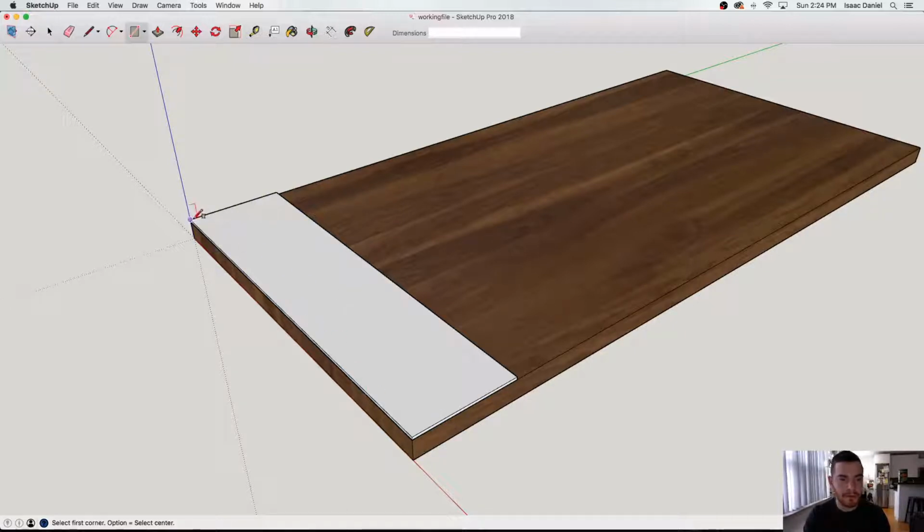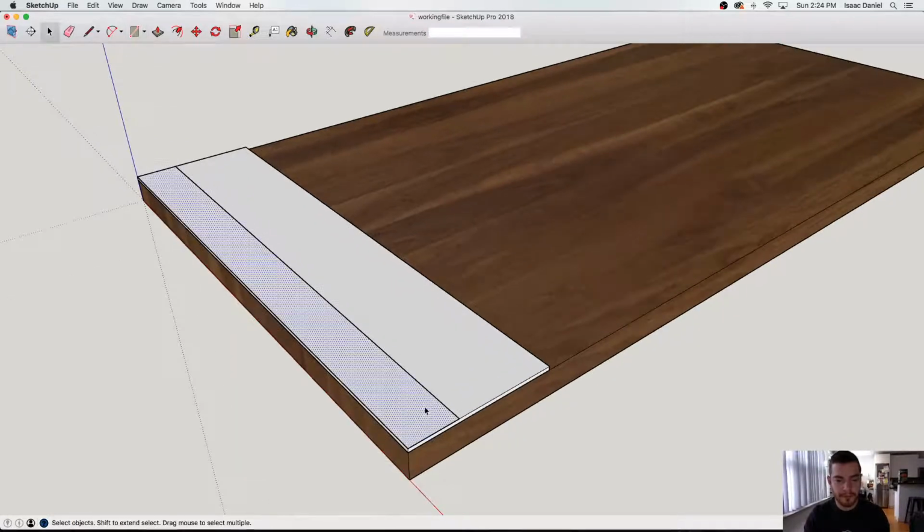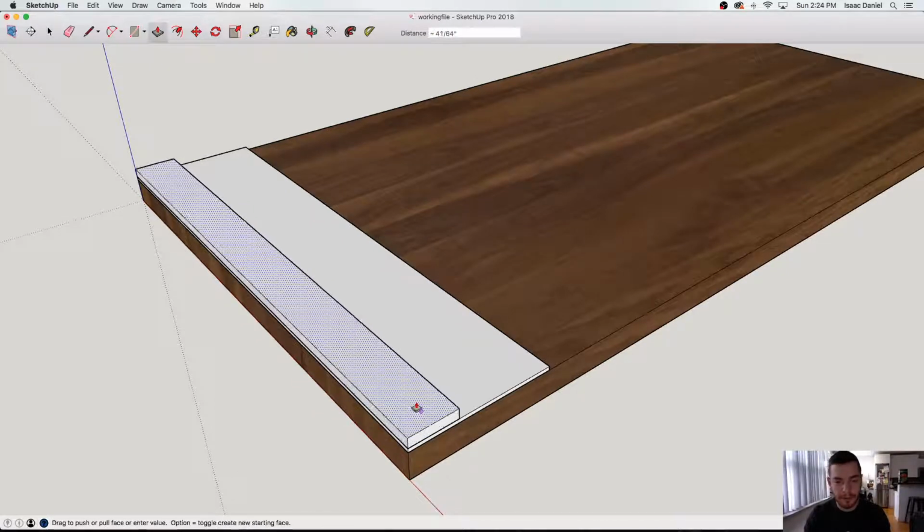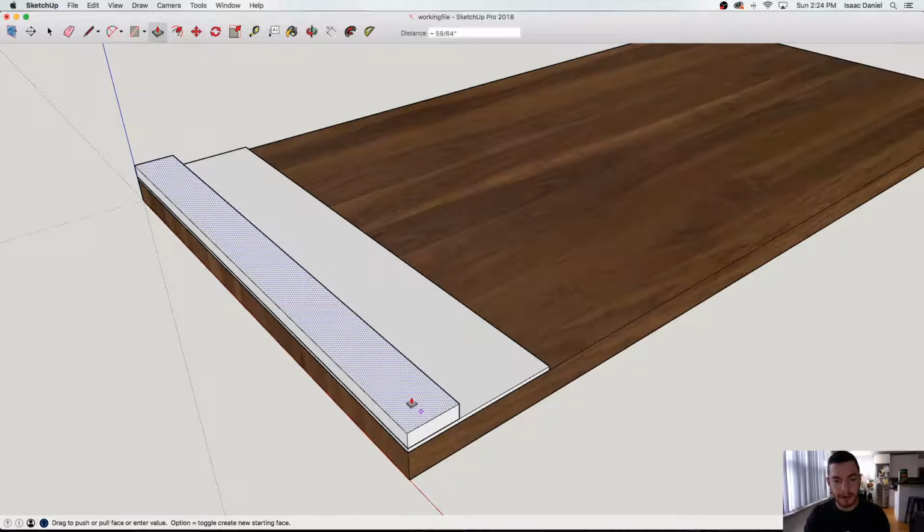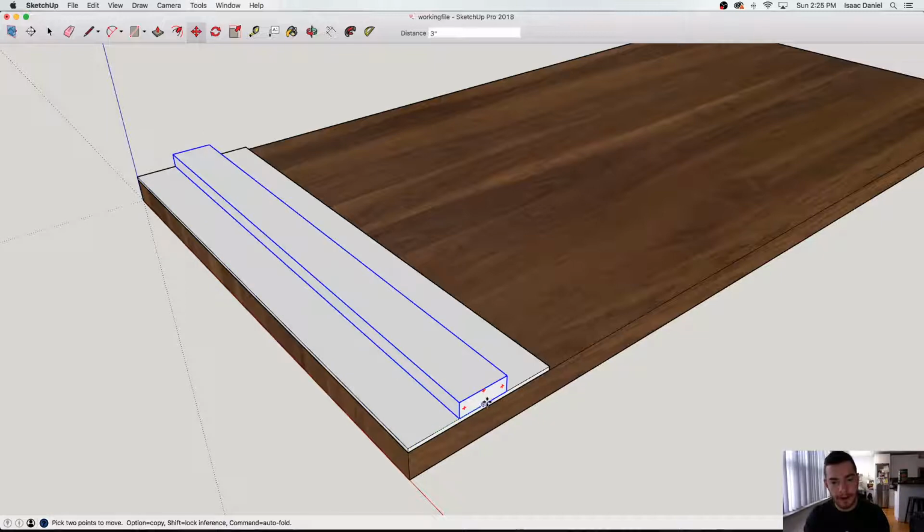What do we say? We're going to make this U shape. So we'll make this U shape. Let's call this 3-inch tube. So we'll make a 3-inch rectangle. Bring back the push-pull tool, and we use P. You can go and select it at the top, but I usually use the shortcut. And there you go. You've got a 3D 1-inch by 3-inch tube. Go ahead and make that a group, and we'll drag it over.